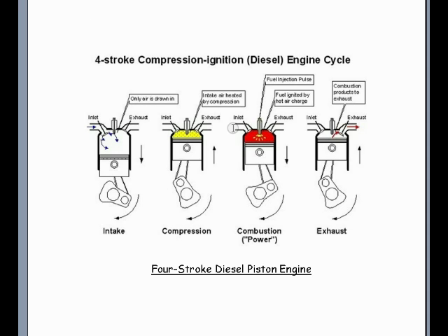Gasoline piston engines with higher compression require higher octane. Octane has no connection to the amount of energy in gasoline. All that octane does is it slows down the speed of the gasoline fuel when under higher compression to prevent explosion of the fuel, also known as detonation or commonly referred to as knock.